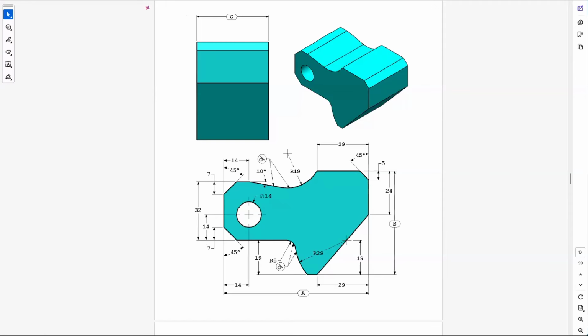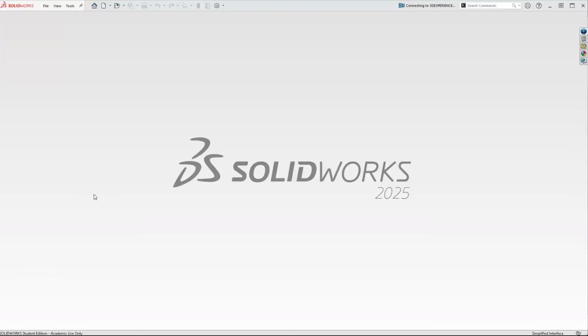Let me shift here to SOLIDWORKS. All right. So when I set up a problem for the CSWA, I think of four primary things. The first most important thing is the actual units. I always change the units first right away. And then from there, I work on it because I'm sure many teachers and many students here have had issues where they did it in one unit system and then they swapped later.